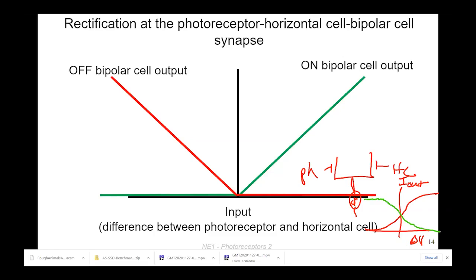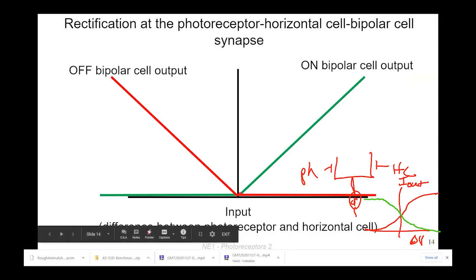Wait, I don't think this is what we're looking for, but couldn't we use a winner-take-all circuit for this? Where's the differential input? I suppose you could, but then it has an extremely sharp response, right? If you use a winner-take-all, it would just shoot up like this.